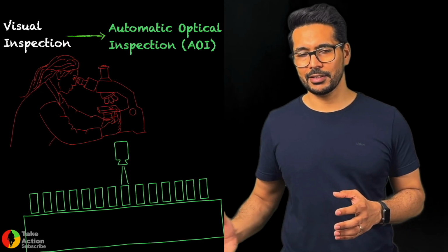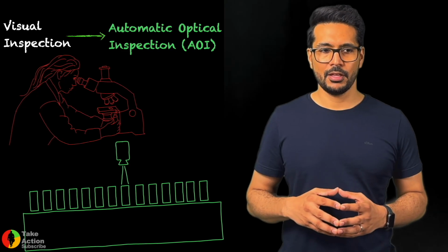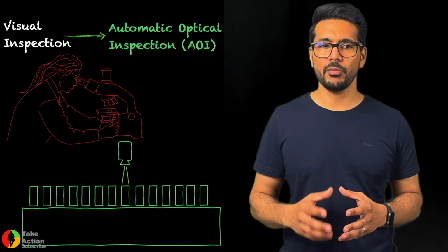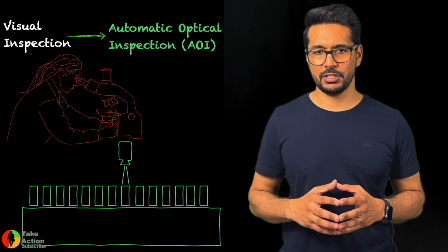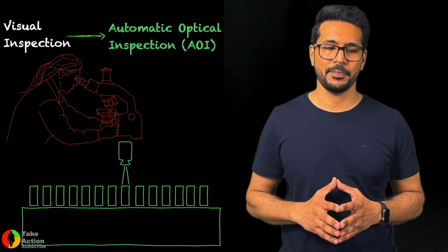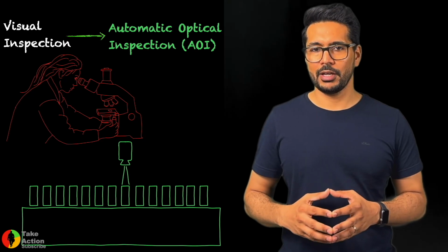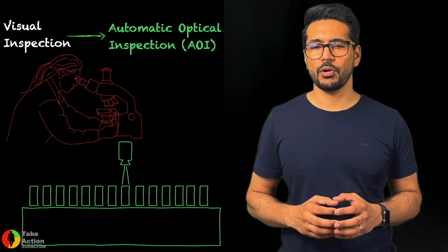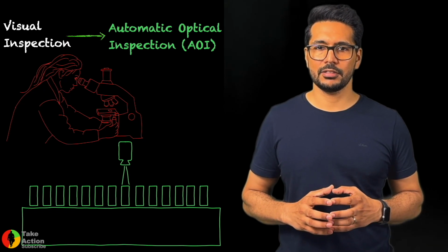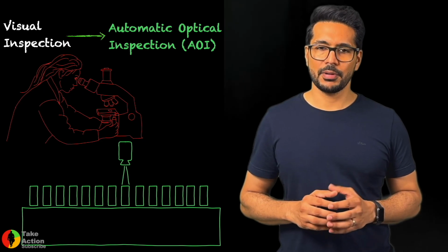If we have a manual inspection process down the line, then it makes sense to have AOI, so that down the line we don't have to do any additional inspection. We save the cost, because normally AOIs are expensive. But in case we don't have any manual inspection down the processes, and only want to make the setup time quicker, we cannot buy AOI. In that case, we can think of a small camera system. There are plenty of cameras available in the market, and we can install that camera in the machine, which can detect most of the errors in the part, not all.